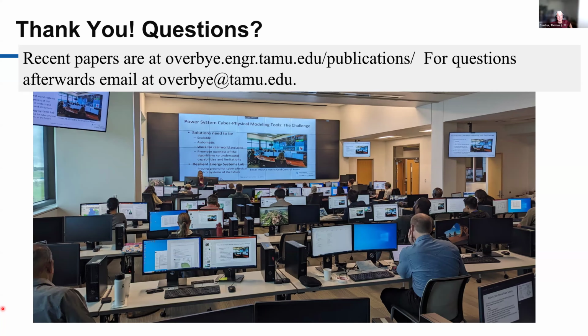Right there, as the questioner mentions, there's a lot of work in Monte Carlo about how many simulations you need to run for a particular confidence level, and the question is sort of confidence in what? In what we're doing here, it's a 993 bus scenario. With that operating point, I think 500 contingencies is good enough to give me a good feel that about 38% of the power flows are going to fail to converge.